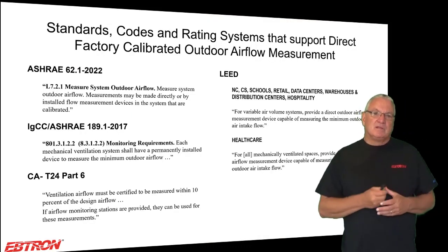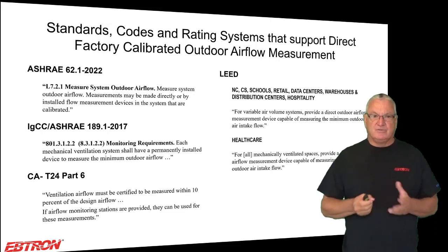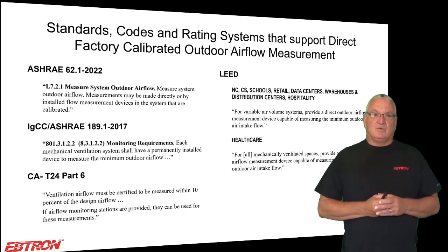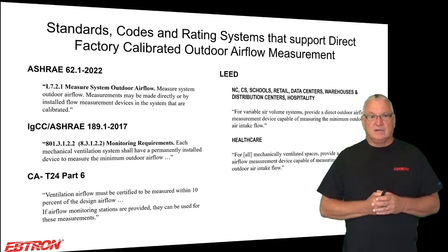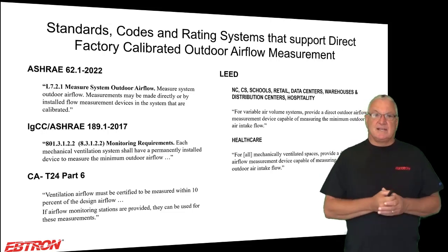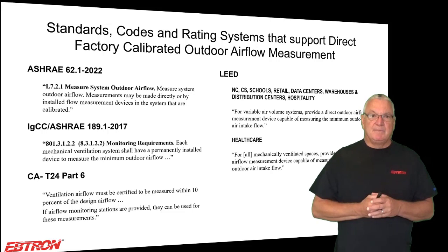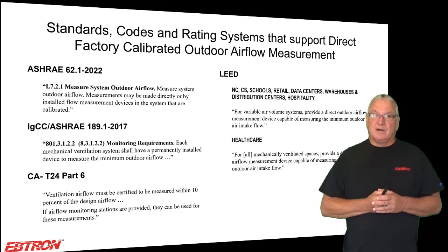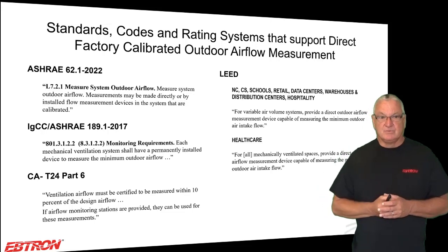When it comes down to looking at dilution ventilation, our opinion is the only way you're going to pull this off is you need to measure it and control it. And we're not the only ones that feel that way. When you take a look at this particular slide, you'll find ASHRAE 62.1, the 2022 version. Its Appendix L, which is for existing buildings, says that you need to measure system outdoor airflow rates to determine whether you're in compliance, and it allows you to either directly measure them in the field, or use permanently installed calibrated airflow meters, which is what we would prefer.